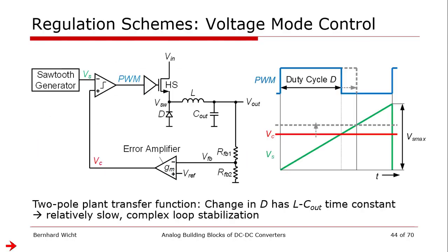Control loop. So let's again put everything together. We have the power stage, our LC filter, and then we hook the output voltage by resistive divider to the error amplifier, which sees the reference voltage here at the positive input to give the reference level for the output.